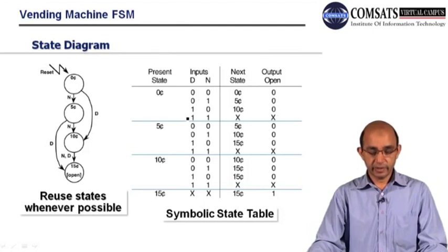And there is a race condition, you can say, as we have race condition in flip-flops. In this vending machine we cannot insert 2 coins simultaneously, so this is not allowed. You can see that we have no next state and no output when both are 1 1. So we are at 0.